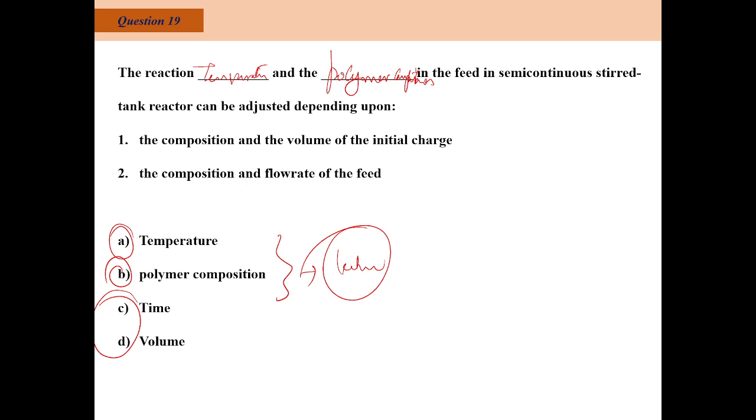So, Shravan sir, is it like this? Suppose in a continuous reactor, the desired molecular weight distribution polymer we are not obtaining in this process. No, actually, we can obtain it, but the only thing is, for example, if I want a narrow range of molecular weight distribution and I fine tune the process for that, then definitely continuous polymerization will help to give you a narrow distribution and a polymeric output also.